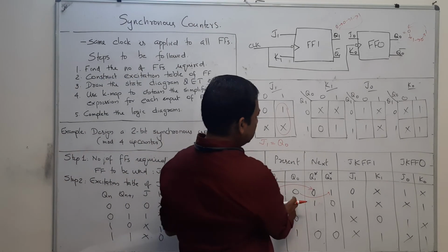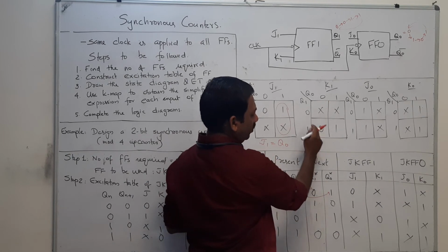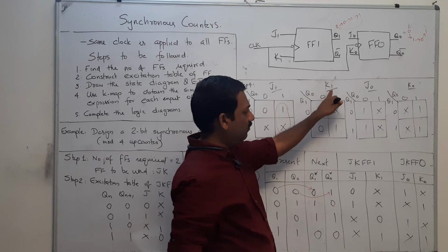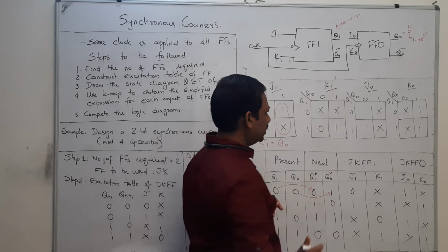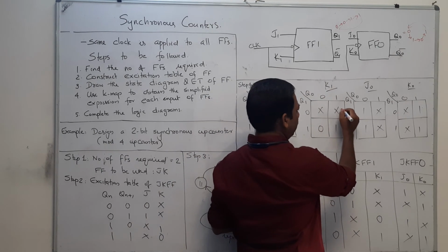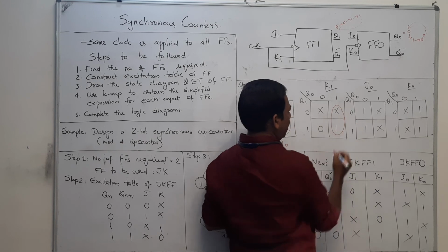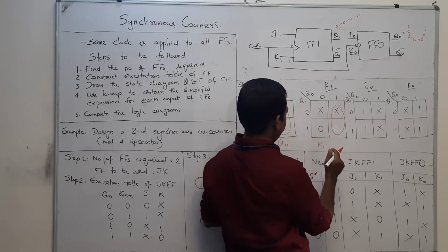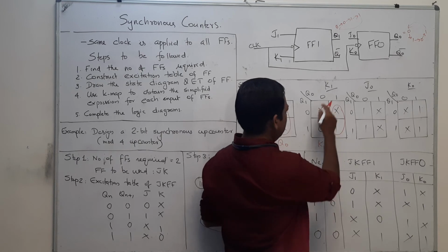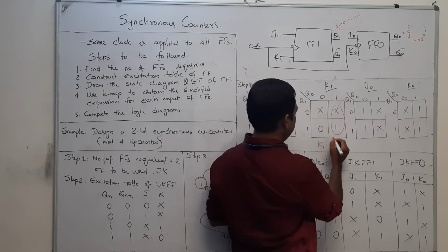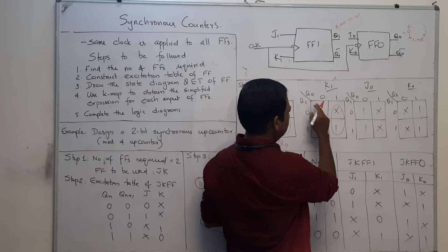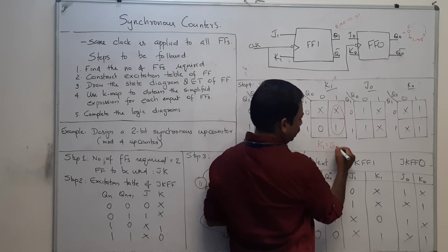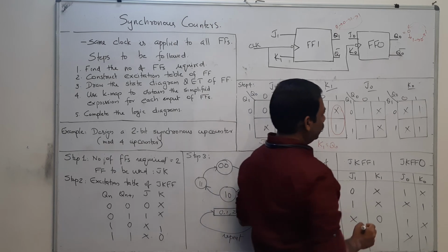Now, using this Karnaugh map, we have entered the details of the Karnaugh map for K1, and using this again, I am going to have a grouping like this, and now K1 is equal to, what is this? K1 again, see, that also is Q0.